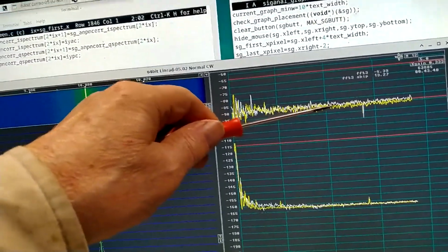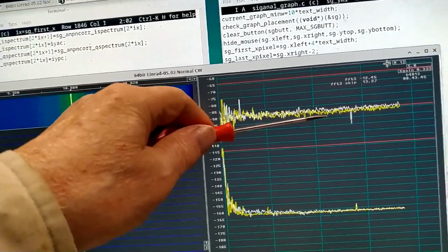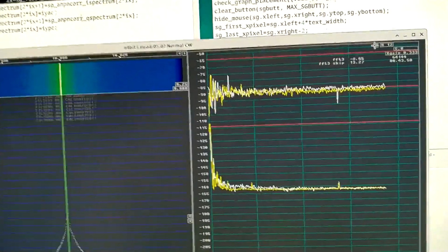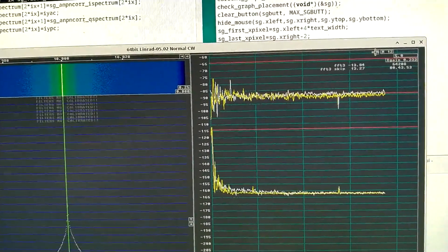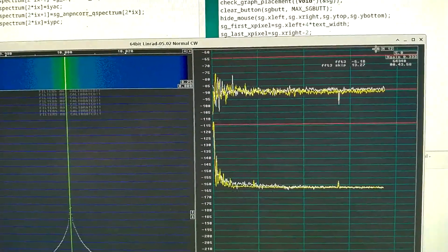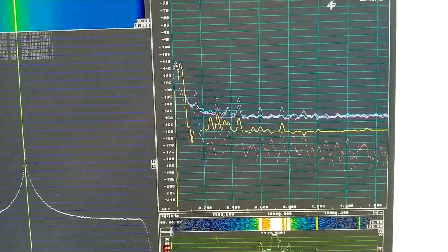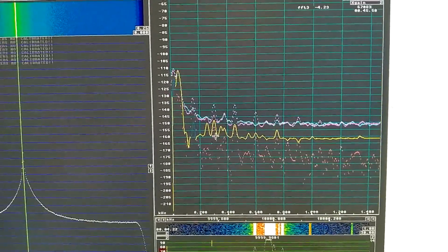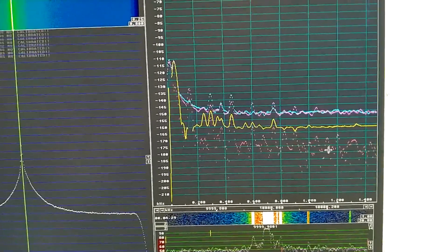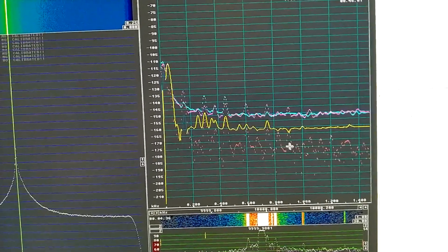So it means that the correlation that is there is at 90 degrees, but it is so small so it cannot be used to reduce the phase noise. So at wide range there is nothing to do using the AM modulation. At close range there are artifacts. You can see the lines in the red in the imaginary part. That is not from the signal source, it is somehow from the SDR IP units.